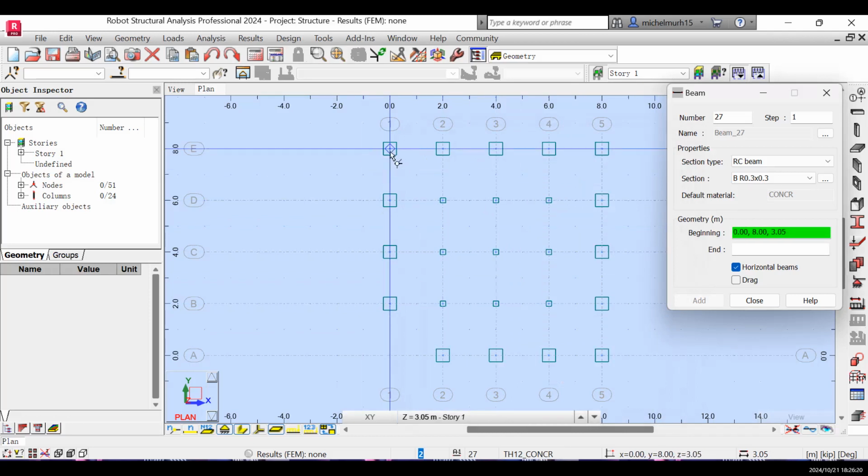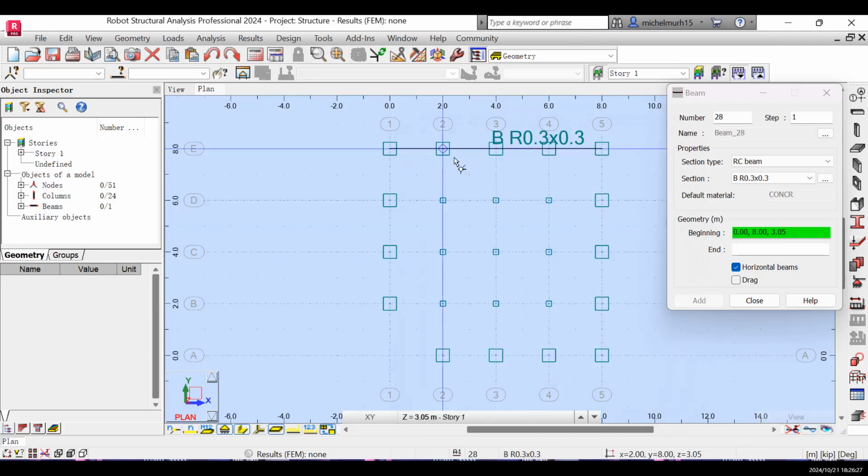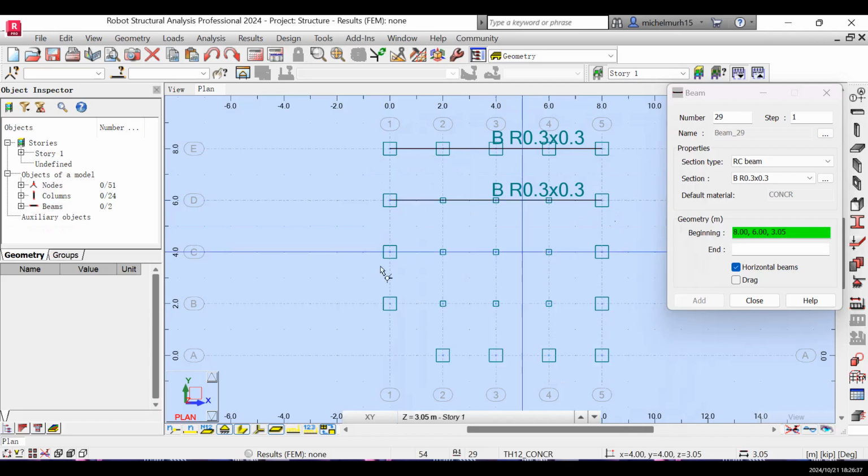my beam. And pressing the beam, just need to put from one extremity to another extremity. So you don't need to press one by one. The computer will align it for you. Just show the computer where the beam starts and where the beam ends, right? And then it's gonna be aligned to all of the columns, right? And you can do it for all of them. All right.